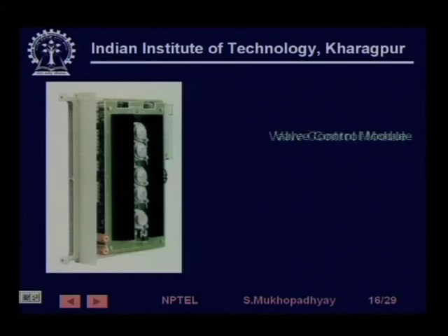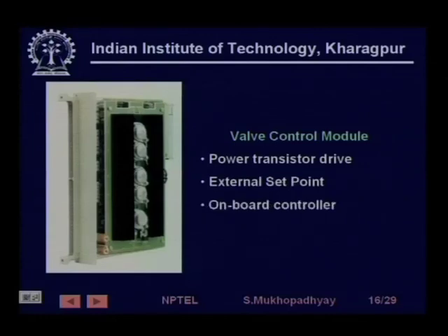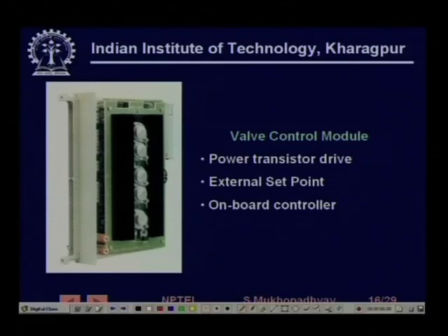This is another controller which is a valve control module. I chose this because I wanted to show the power transistors on this. So, you can see the power transistors. It has to drive a valve, probably a hydraulic servo valve or something, so it has to pull a solenoid, create some force, so that the piston moves.